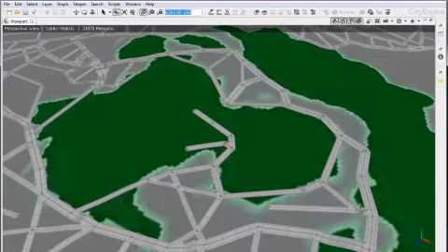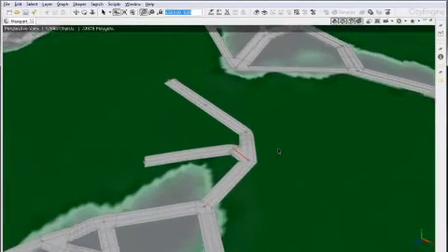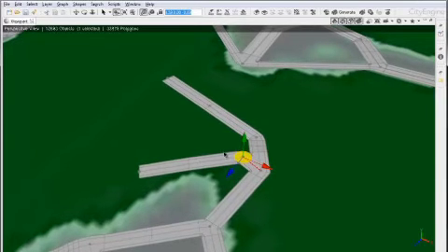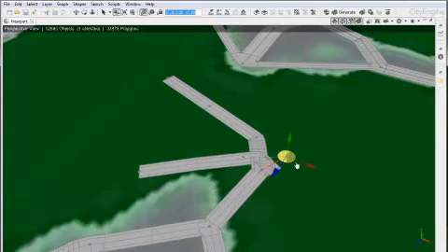In the third part of the tutorial we are talking about the cleanup tool for the street graph segments. It can happen that, depending on how the graph segments are laid out or how they lie in the scene, the dynamic city layout system cannot always produce a correct set of shapes for them, as within this example here. The red line actually indicates the graph segment which causes the issues. So we could manually go in and select this node here and move it out of the way so that the shapes can be produced correctly.